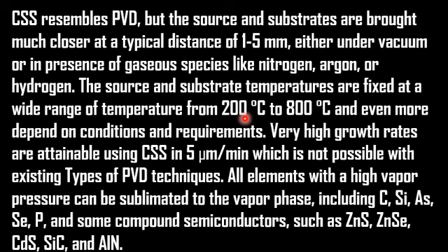So basically the temperature in the closed space sublimation process is required for both the substrate as well as the precursor material. In conventional closed space sublimation, usually the sublimation is done at a slightly higher temperature, but the substrate is kept at room temperature.